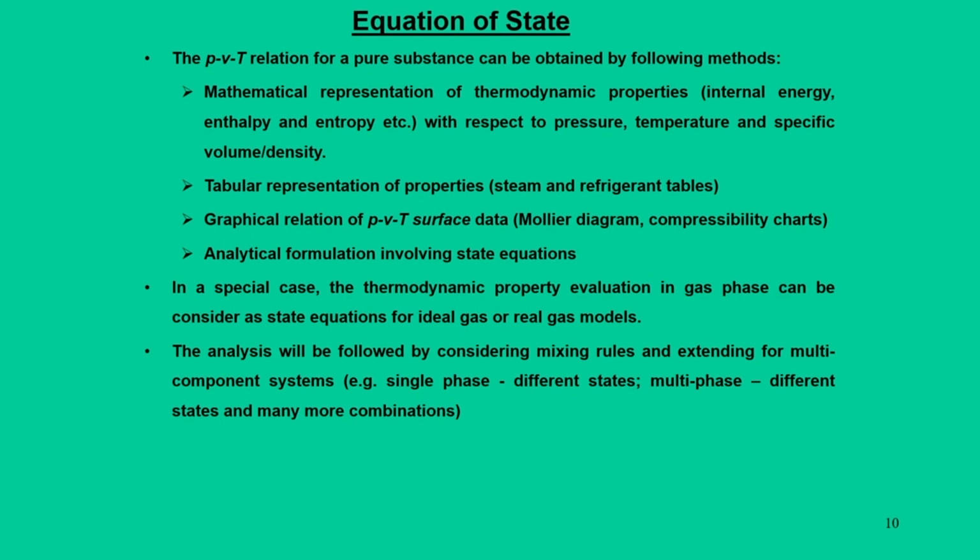However, their relative accuracy may change, and while doing these analytical formulations, our model comes in, what we call the real gas model. So, in a special case, the thermodynamic property evaluation in the gas phase is normally considered through equations of state for ideal gas or real gas models. These gas models are also applicable to mixing systems, multi-component systems.